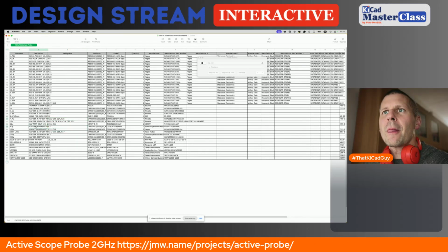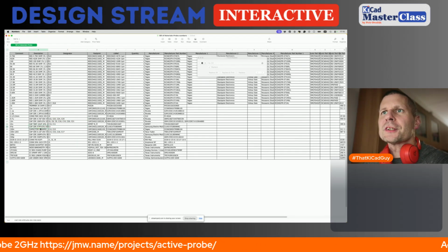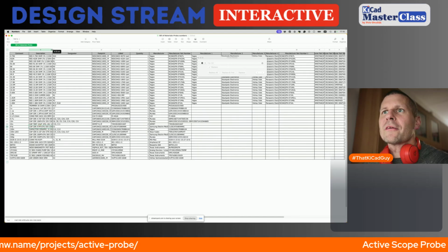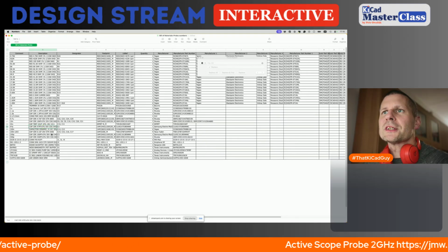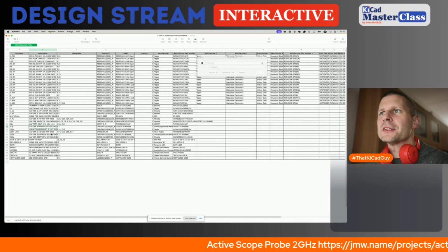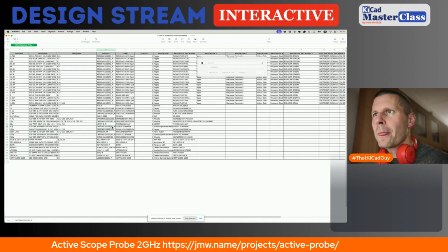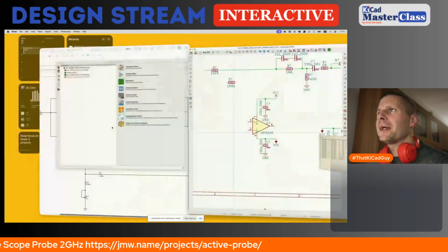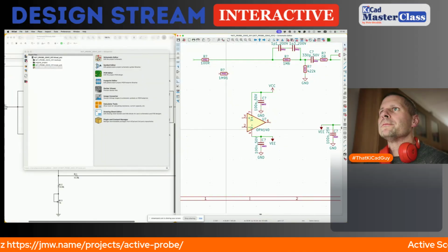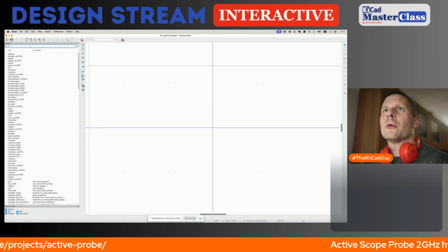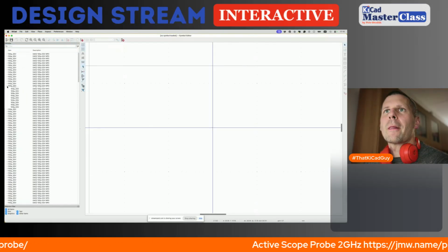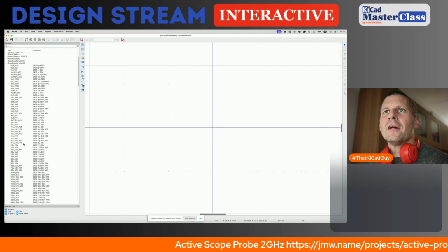C2 is here. It's a 47 pico rated with 50 volts, C0G or NP0 in 0402 package. So I have to create a new component for our usage.